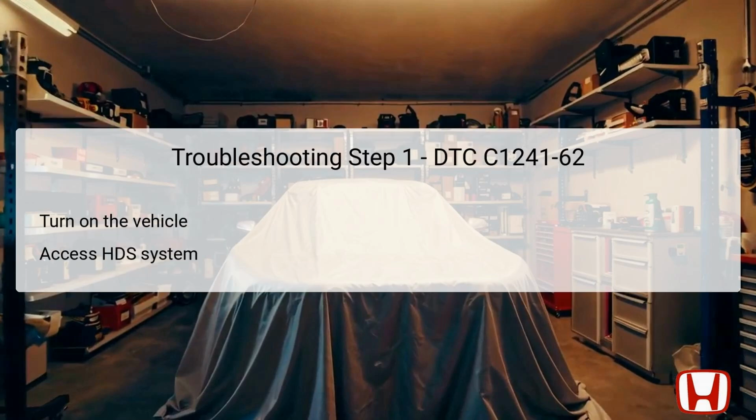The first step in diagnosing DTC C1241-62 is to turn the vehicle's ignition to the on position, ensuring that all electrical systems are active and ready for testing. This allows the Honda Diagnostic System, HDS, to be utilized effectively.